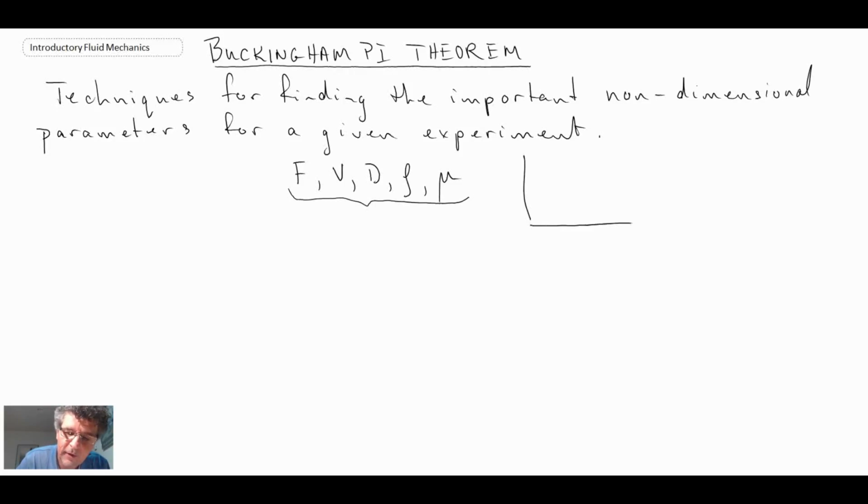And I talked about collapsing data from a pi parameter 1 to a pi parameter 2. And you might have more than just two pi parameters, but if you could collapse your data into a line, or it could be a curve or anything like that, that is good, because then that relationship can characterize many experiments, and as engineers we like having that.